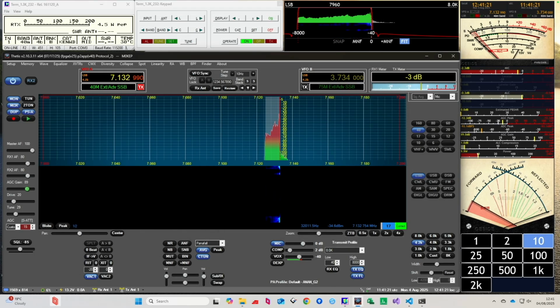And there's one important thing to note about Thetis, is when pure signal's on, if you use pure signal, it can affect the monitored audio. In fact, it normally does. So I'm just going to turn off pure signal now while you're listening, and see if you can hear the difference there. There should now sound a bit clearer. So I've just gone and done that last recording with pure signal on, which may have been adding a bit of distortion to my audio. So I'll just demonstrate that on and off again there. So yeah, listen with pure signal off when you're adjusting your audio.